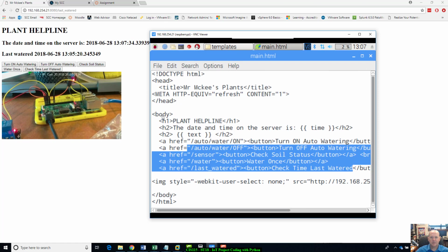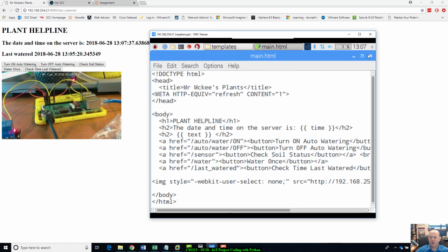And with my Raspberry Pis, I was having a bunch of issues. A lot of times, if a Raspberry Pi is acting up and it's intermittent, I have spliced in some power cables to power my Raspberry Pis. They're not that great, so if the voltage drops too much, they start acting up. So that's what happened, but I fixed that now. Hopefully it's fixed for the time being. But that's pretty much what you guys are going to do.